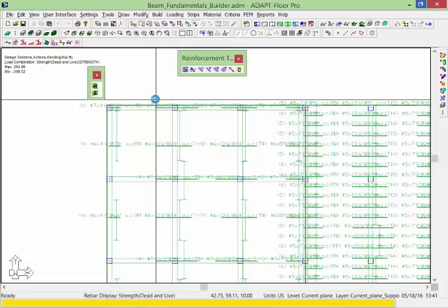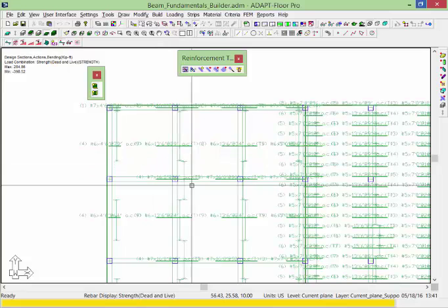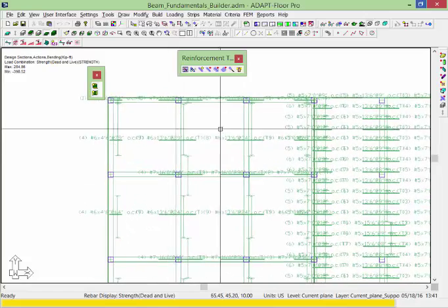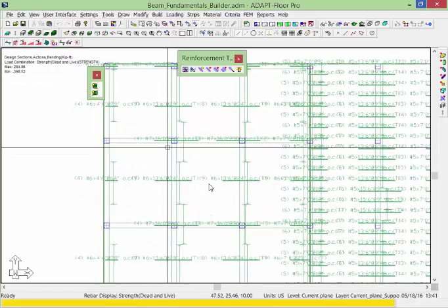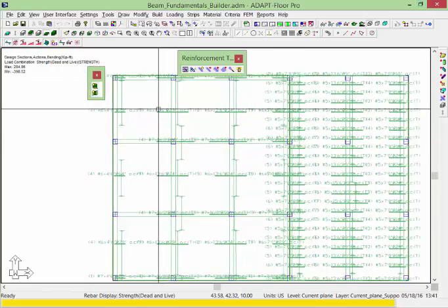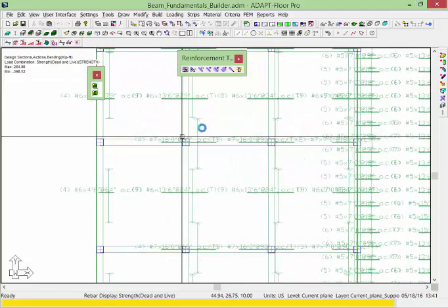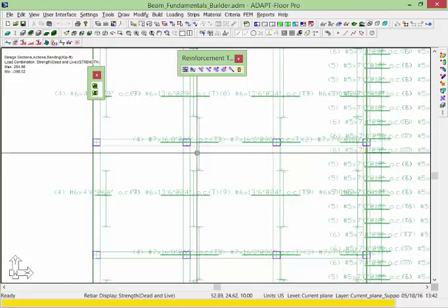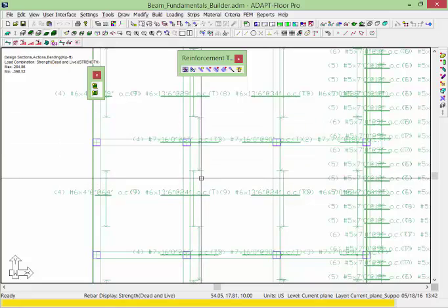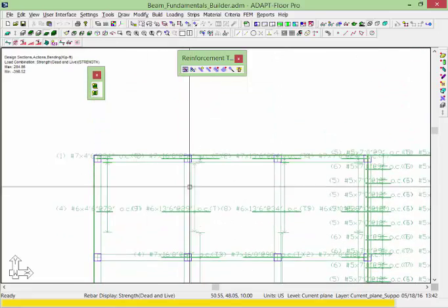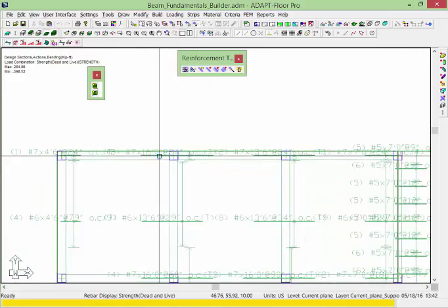The slab engulfs the beam, or the beam engulfs the slab in this case. So all of the reinforcement here is shown as distributed as well, and would be placed over the width of the actual flange of a T-beam, or the design strip width in more generic terms.